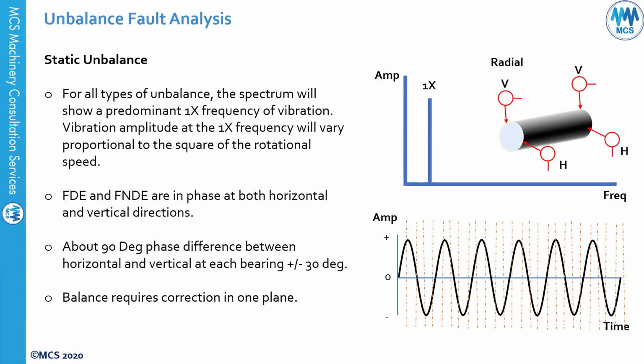And when you see high imbalance vibration on any machine, like let's say on one of the fans, blowers, or pumps, it's pretty easy to see a few small-amplitude harmonics as a result of, let's say, looseness. And the looseness will come as a result of the high vibration caused by imbalance.